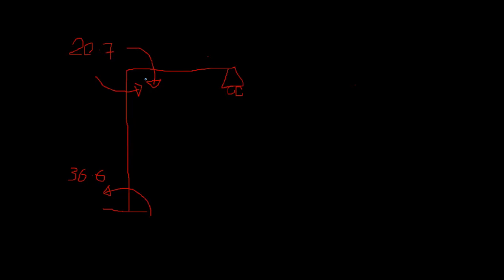Okay. So yes, you can draw that value on the side where it's shown by the arrowhead. So this is telling you should draw it in the lower side of the member. So that's going to be 20.7. It's showing for this member. It should be in this way, 20.7. So 36.6, the arrowhead showing in this way, not this way. It's 36.7, right? So this is your support bending moment diagram, right?